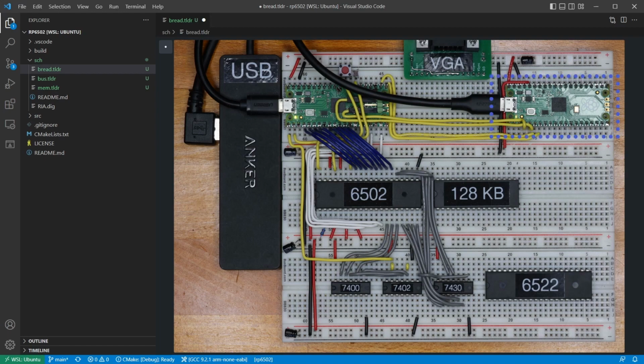This PyPico is for video, but it's only running the debugger right now. This one is what we're working on. It does pretty much everything except video. The PyPico connects to the 6502 like other interface adapters. Chips like the PIA, SIA, TIA, or VIA. I needed a file name and RIA wasn't taken, so that's what I'm calling this connection.